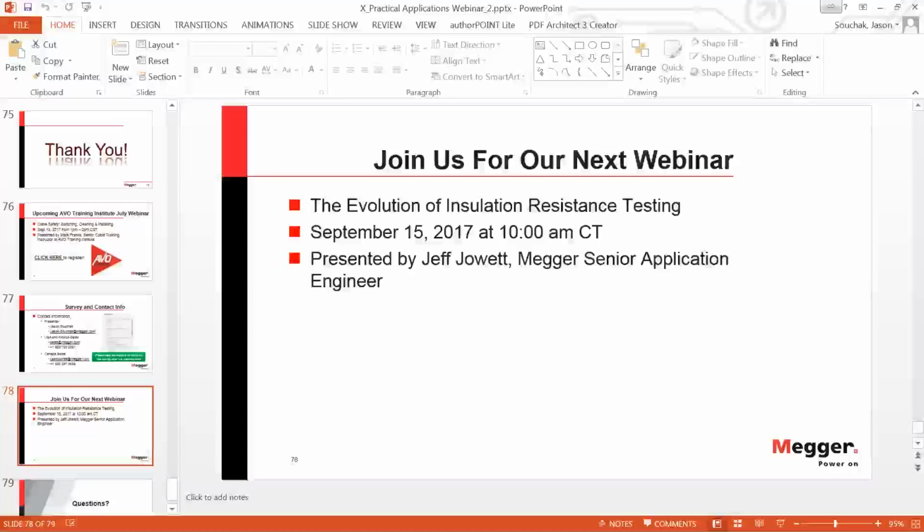Thank you, Henning. Next question is for Jason. For failed cables, what is the minimum length that is required to analyze the failure? I'll answer this based on the individual tests that we talked about. For VLF withstand testing, I can test as small as you can make them. Any cable that you can put 2 terminations on and have something between, VLF withstand testing can test it. Practical length, really, 30 feet. I don't think too many people have something much shorter than that.